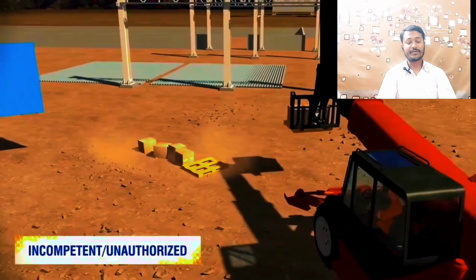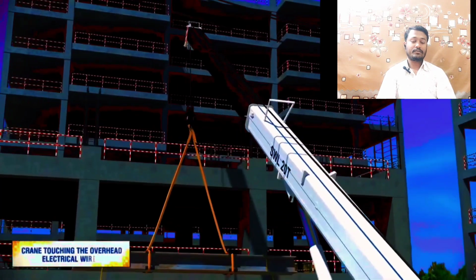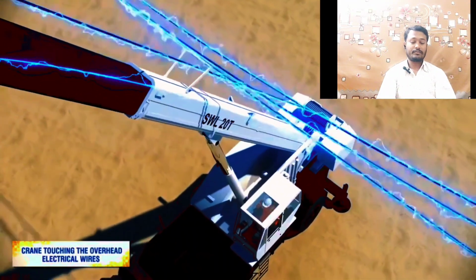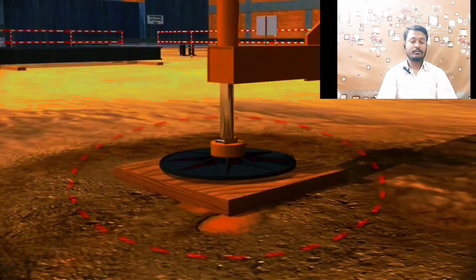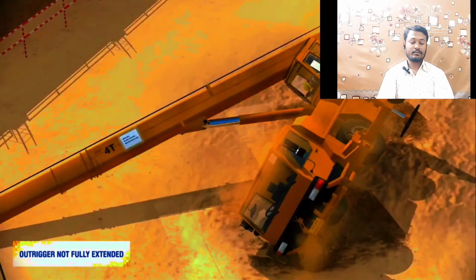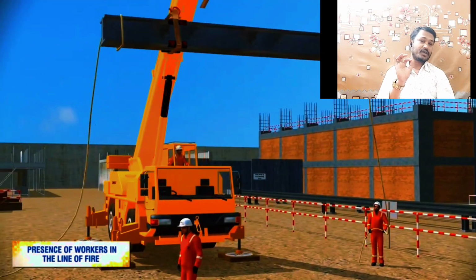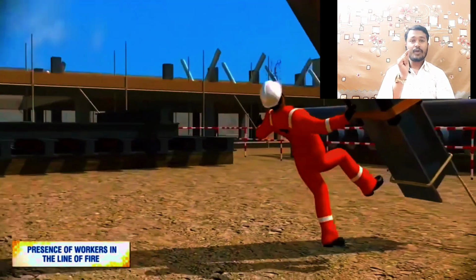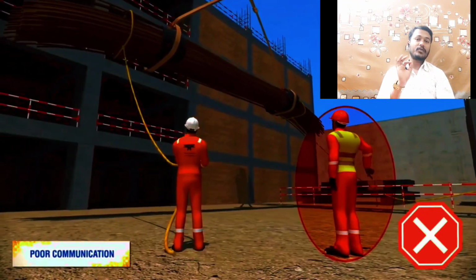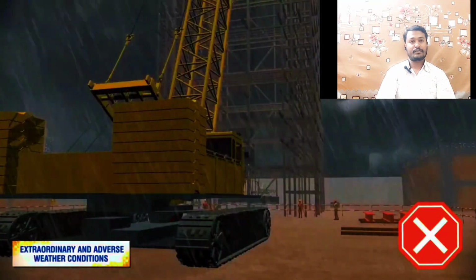Allowing incompetent or unauthorized staff to use the equipment. Any part of the crane touching the overhead electrical wires, which can result in electrocution. Grounds not being firm and outrigger not fully extended, which may result in tripping, imbalance or trapping of the crane. Presence of workers in the line of fire. Poor communication between banksman and lifting equipment operator. Using equipment in extraordinary and adverse weather conditions.